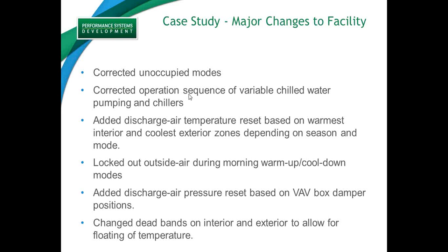They corrected operation sequencing of the chillers. Sometimes you have 2 chillers coming on first thing in the morning instead of staging them. A lot of times resets on the discharge air, or just resets in general of your static pressure, a lot of settings, are either not set or they've been overridden over time.